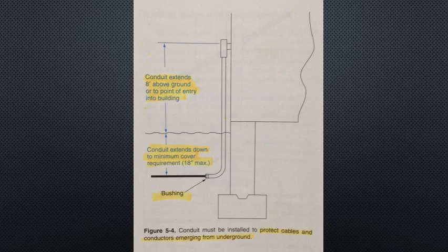Splices and taps are permitted in buried conductors and cables. Be sure to use materials that are suitable for underground use. All splicing materials must be suitable for the conditions and environment in which they are installed.